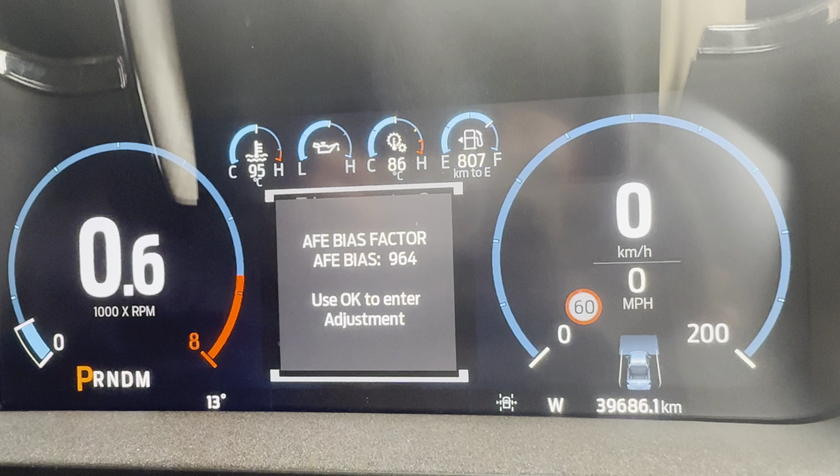Once you've done that, you can start adjusting the number, and you can do it basically in percentage terms. So if the truck's reporting 1% better fuel economy than actual, then you would lower this number by 1%. When you adjust this number, you may find eventually that you've reached a point where the truck is reporting worse fuel economy than your hand calculation, in which case you've got to raise up the number again. So it's just a matter of fine-tuning. I ended up, as you see there, at 964 for my number, and the way you change that, of course,